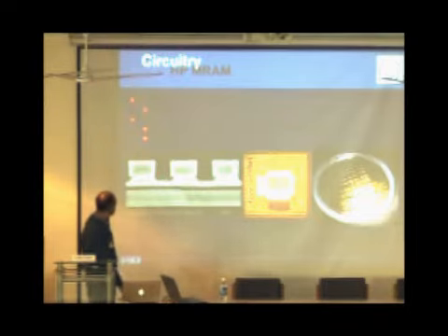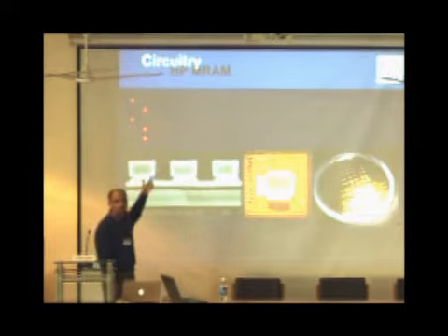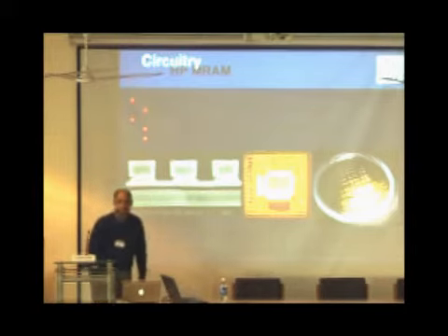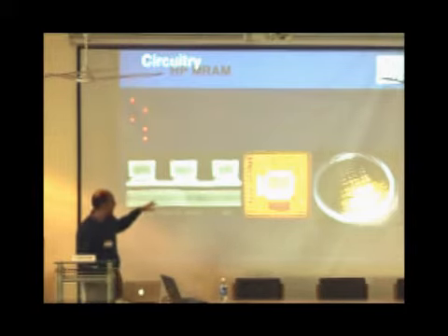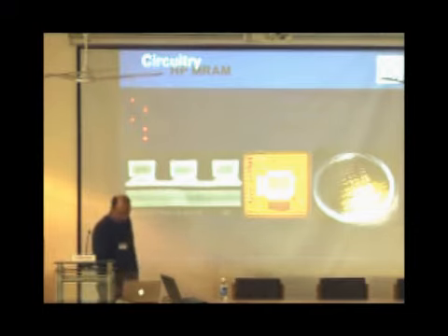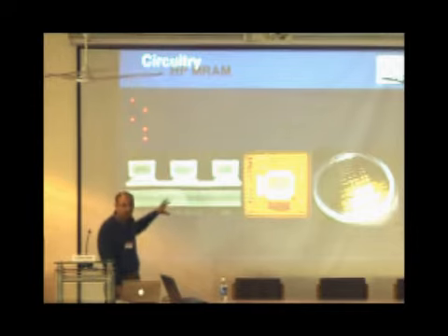So this is planarized copper interconnect layer 1, and this is copper 2, and this thin black line is where the magnetic tunnel junction layer is stored. So it's planarized and made in such a way that if you wanted to make multiple layers, you could potentially stack it. This demonstration chip was done on a 6-inch wafer, and each chip is 1 gigabit, including all the working CMOS with this. However, this was designed to be high density, low speed.